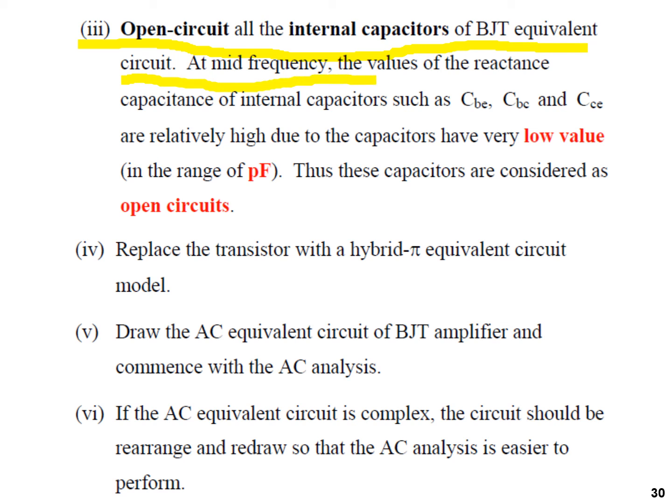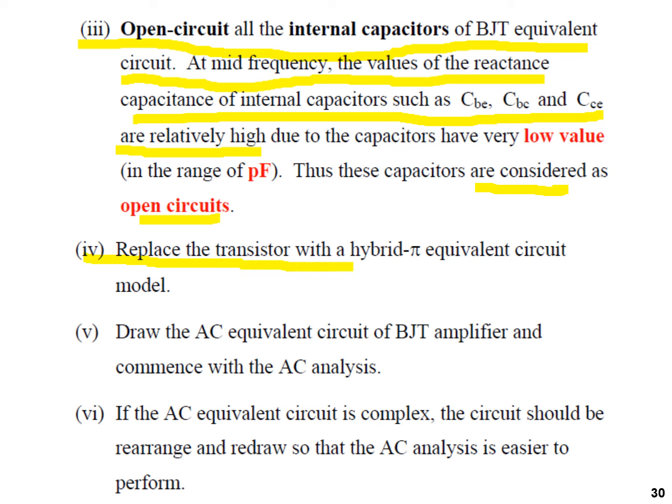At mid-frequency, the reactance of internal capacitors such as CBE, CBC, and CCE are relatively high and considered as open circuits. Fourth, replace the transistor with a hybrid pi equivalent circuit model.